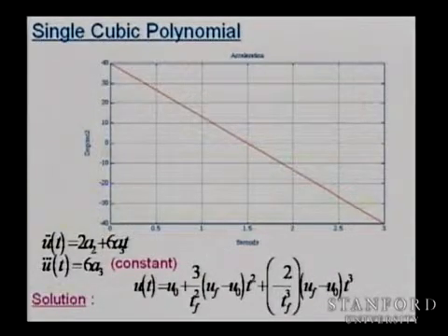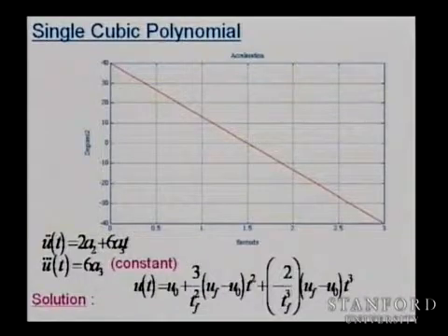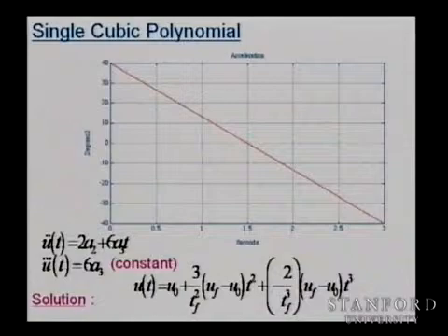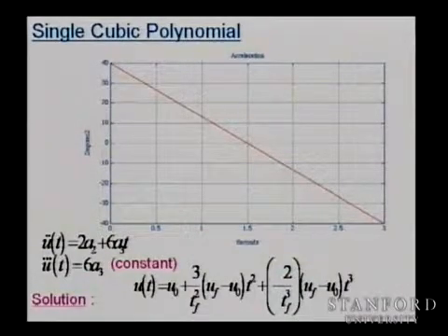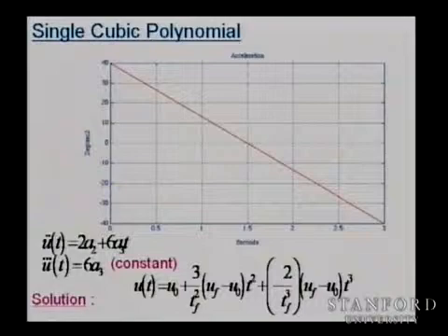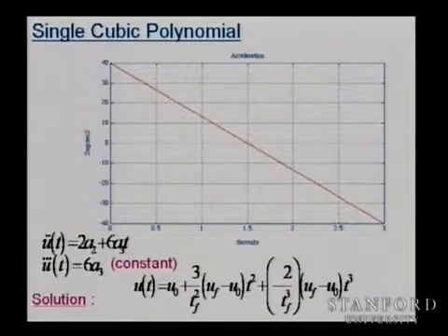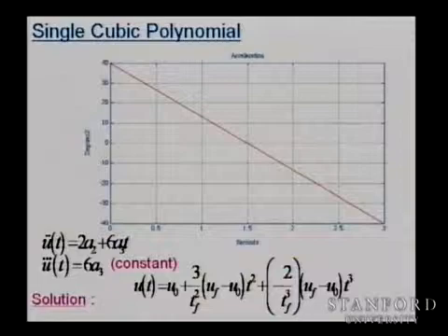So basically, here is the solution. I'm not going to spend the time to derive it right now, but it's pretty simple. Two linear equations with two unknowns, a2 and a3. These are the values of a2 and a3. a1 we set as 0 because the velocity at the beginning is 0. And a0 is u0 because that's the position at time 0. So as you can see, the trajectory depends on the initial position, the goal position, and the time that we want to traverse that segment. Okay? Pretty simple so far.